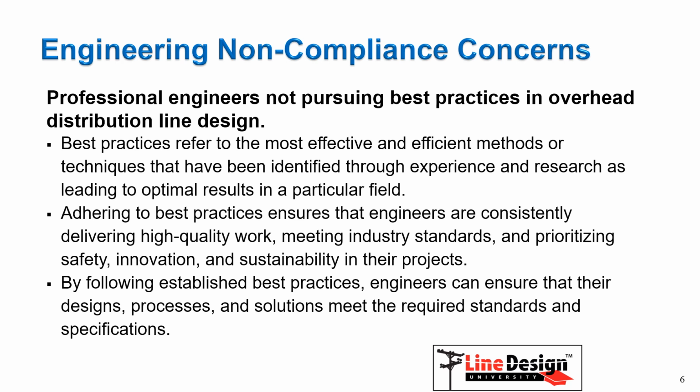By following established best practices, engineers can ensure that their designs, processes, and solutions meet the required standards and specifications. Best practices include engineering design documents as a final design, profile drawings, documenting system-wide National Electrical Safety Code calculation results, having a superior joint use program, and system modeling to identify, document, and correct all National Electrical Safety Code violations.